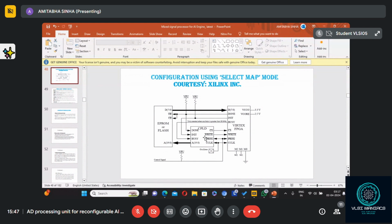Similarly, for a CPLD, you take a CPLD chip, using the Verilog or VHDL you program it, test it, synthesize it, all this. Then again, this will be on the board. And for designing the board, what you have to do? You have to do the PCB layout. Using PCAD or OrCAD, these design automation tools, you can design the PCB and place an order for the PCB. Then once you get it, you test it.